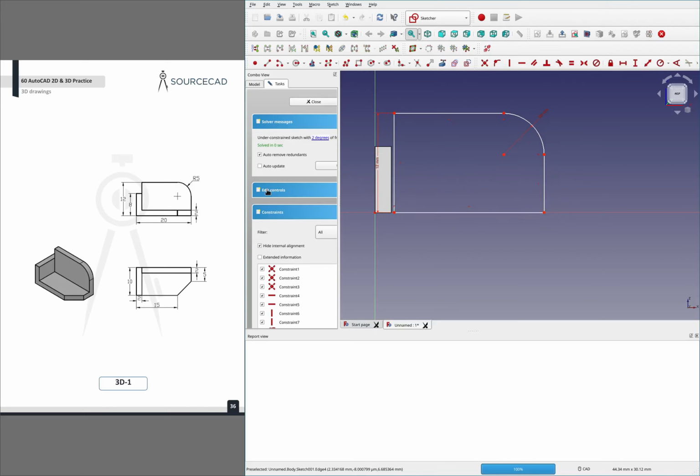And then we need to reference, because this edge here intersects this edge, but it doesn't go all the way back to the origin. We actually have to grab the dimensions. Use the grab dimension tool, and you can grab the points off of this other side here, and we'll make those coincident with the C button.